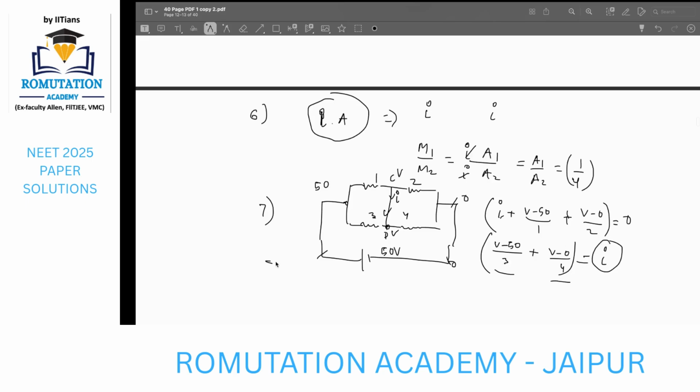So if I make use of this equation over the above equation, I can easily solve that one. So (V minus 50) by 3, plus V by 4, plus (V minus 50) by 1, plus V by 2 should sum out to be 0.